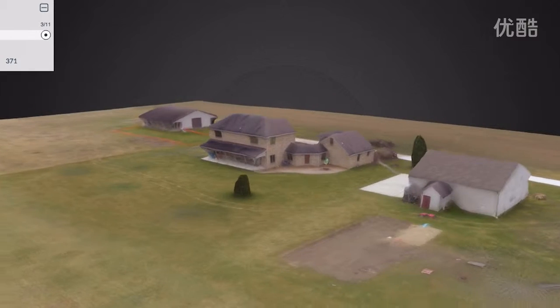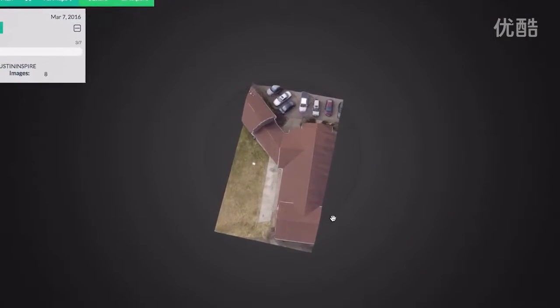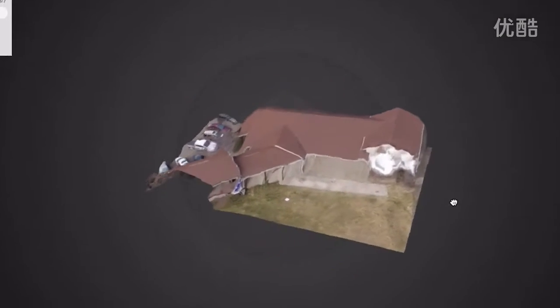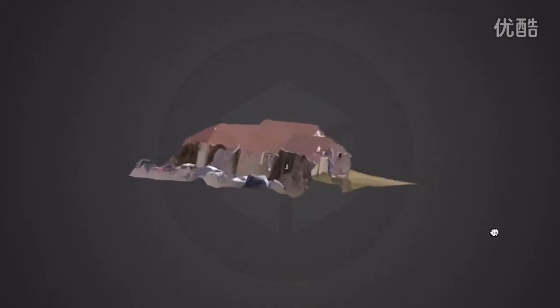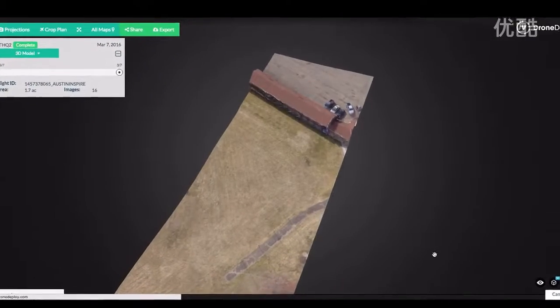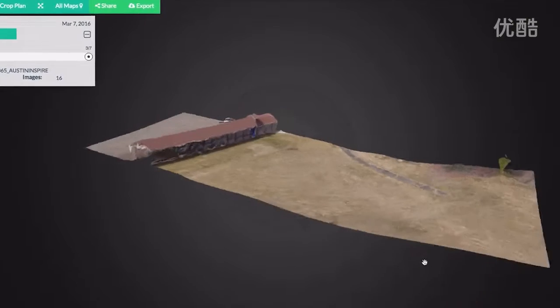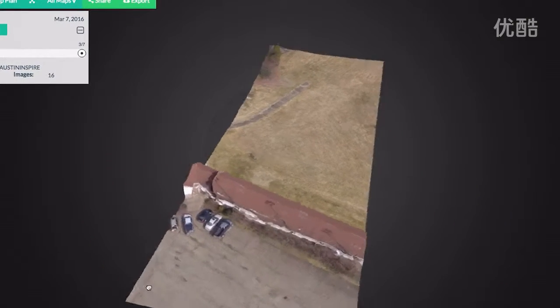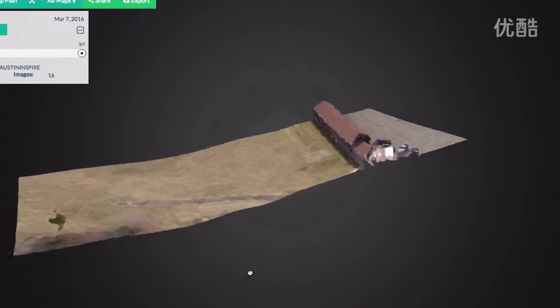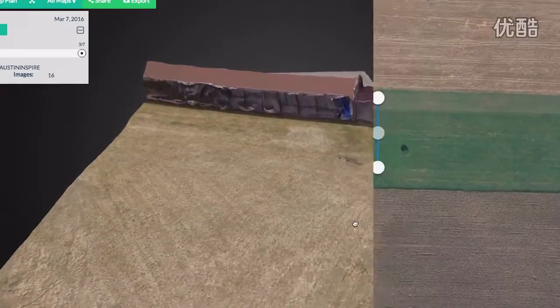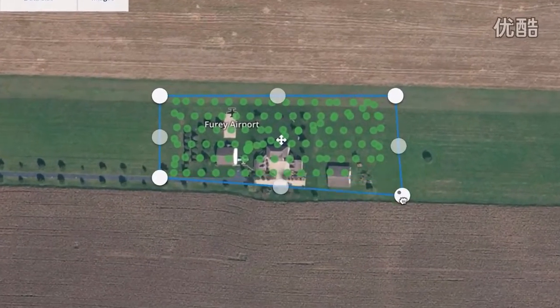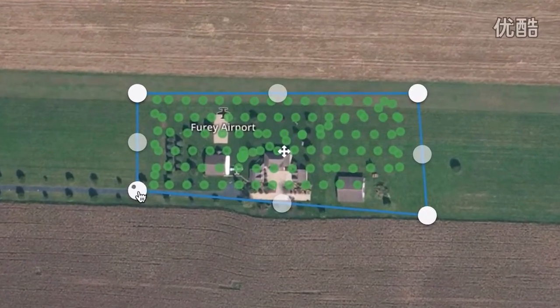Overlap is extremely important. The very first model I did here at the shop was like 8 photos, maybe 40% overlap or less. So I started doing like 80% overlap. And for a small area, that's okay. It doesn't take that long to do about 10 acres or so, even with 80% overlap. That's also front and side overlap. So it's taking pictures sooner going forwards, and overlapping them more on the side.